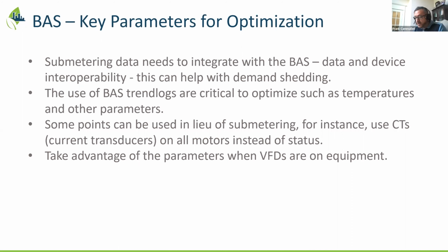We'd like to talk a little bit about using CTs, current transducers, instead of statuses. I have a bit of a history with building automation systems. There used to be status points that would just recognize that power was going to a motor, and you would think it's actually operating, and in some cases it is, and sometimes it may not be. So that's becoming commonplace, as well as now many fans and pumps and so forth have VFDs, and you could take advantage of that, which kind of brings me to